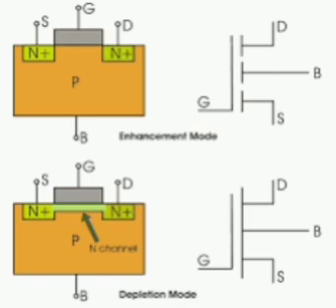Junction capacitance Cj equal to A epsilon by W, where A means area of cross section of diode, W means width of depletion region, epsilon means permittivity of material. Depletion layer in a PN junction behaves as a parallel plate capacitance, and capacitance is given by Cj equal to dq by d(V naught minus V), that equal to A by 2 into root over 2q epsilon Na Nd by (V naught minus V) into (Na plus Nd). 2q epsilon Na Nd is the numerator, (V naught minus V) into (Na plus Nd) is the denominator, where V means applied voltage, A means area of cross section. Cj is directly proportional to 1 by (V naught minus V) whole power 1 by 2. Cj is voltage variable capacitance.